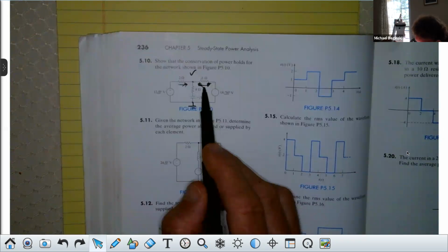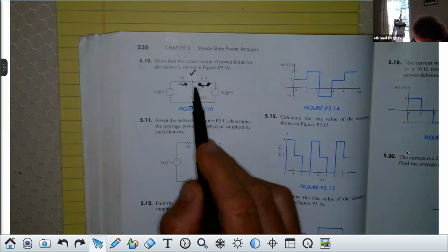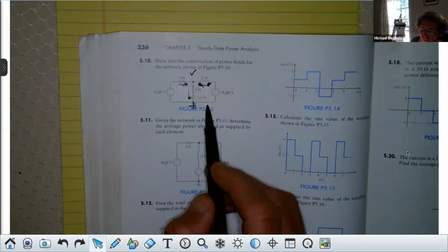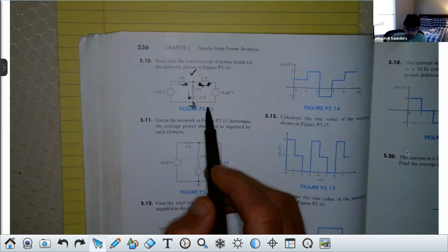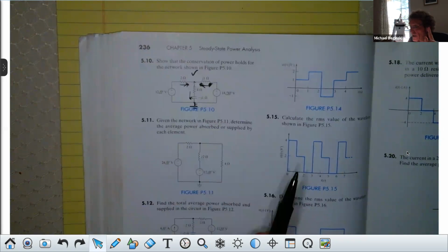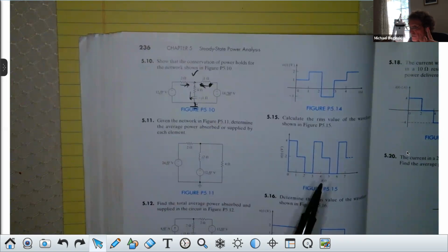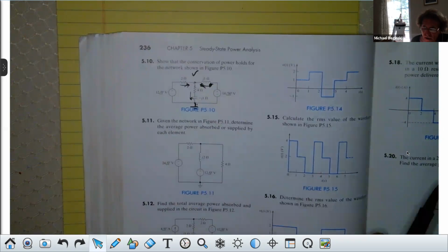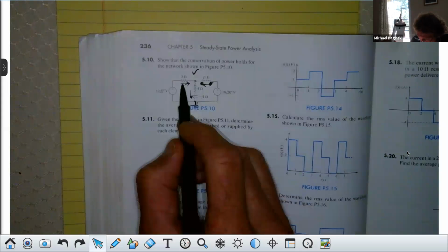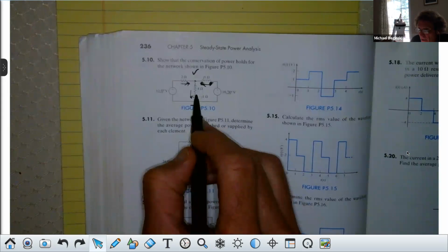And it would equal this current, right? Coming through here, which is just V divided by 4 minus J1, isn't it? And you could solve for V. That's one equation, one unknown, correct, class? Now, once you solve for V, you could go back a step and calculate that I and calculate this I, right? Are you with me?